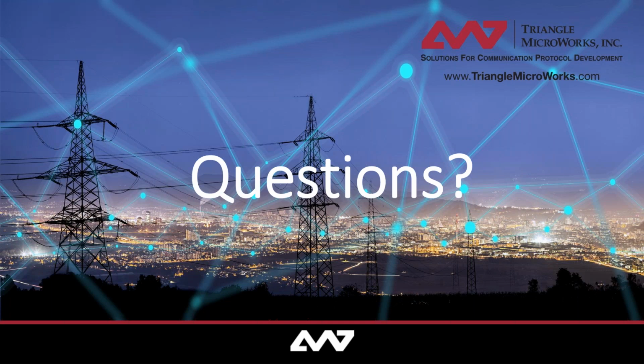So yeah, I can take over that one. There's a few ways. Let's talk about both the test harness and DTM. In test harness, one of the last demos that we'll be going over today is scripting. And Steve, correct me if there's a better way, but how I would do that in test harness is you could just write up a quick script to change the values, and then you can use the previous value as the new value. If you have an analog value, you could increment that by adding a certain flat value to it, a random value. I mean, with scripting, you have all the power in the world, and you could just pretty much run that to allow changing. And the same thing could be done in DTM.